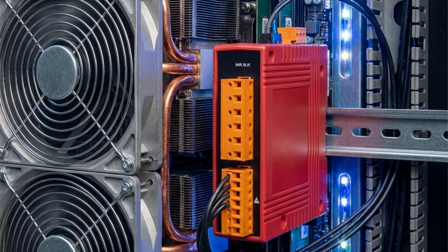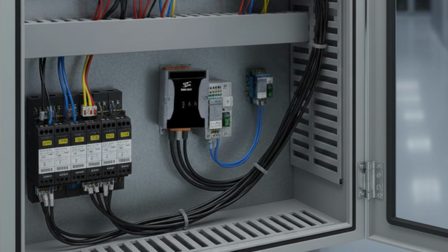Even power meters tied into cooling systems often run serial in the field but report through TCP once aggregated. And if any of that data needs automated logic like triggering alarms, switching equipment, or running conditional routines, edge controllers such as WISE units can sit on the TCP side, interpret the data coming from gateways, log it, and react to it automatically.